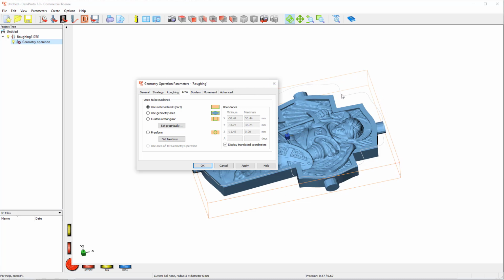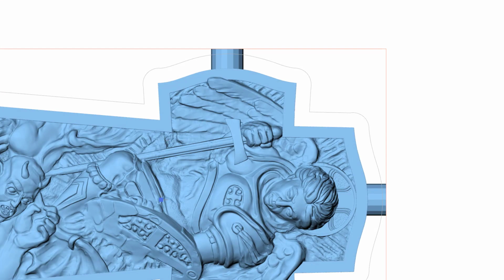You would see a hollow in the wood with the cross sticking up proud, and that's a perfectly valid way to cut as well. For me, I always use a curve because every extra movement is more time on the milling machine. If you're sitting cutting out this area here for nothing, and you didn't need to cut it out, it's a pointless exercise. So I go in and I set it freeform.